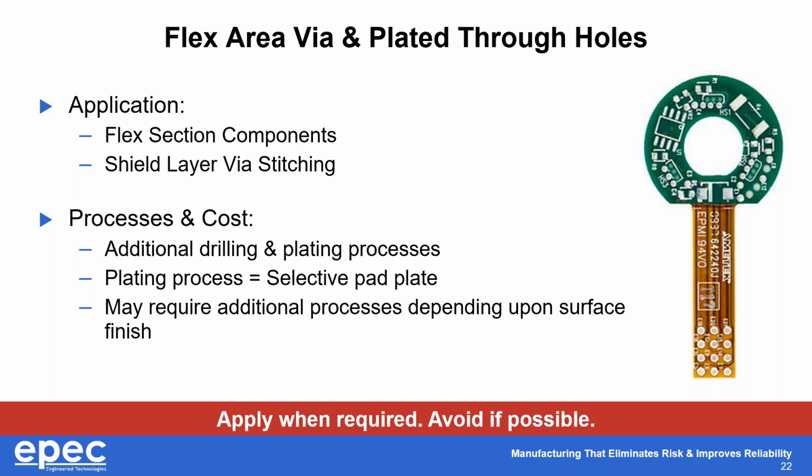And depending upon the surface finish, you may get into some masking issues where you have to mask off the work that you've done or the features on the flex circuit, which again can add some significant process steps and costs and complexity to the design. So to summarize, it's a design element that's available, but we strongly suggest to our customers that it's applied when it's required, and you make an effort to avoid it if possible.